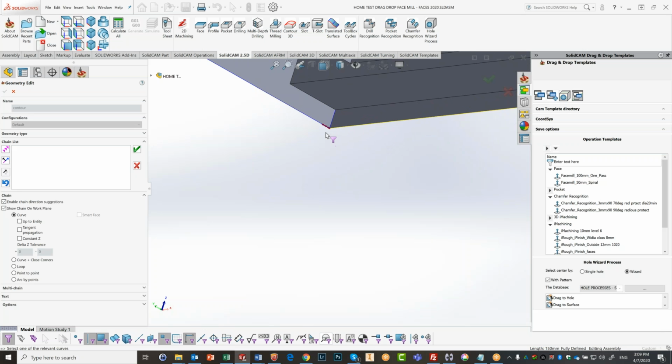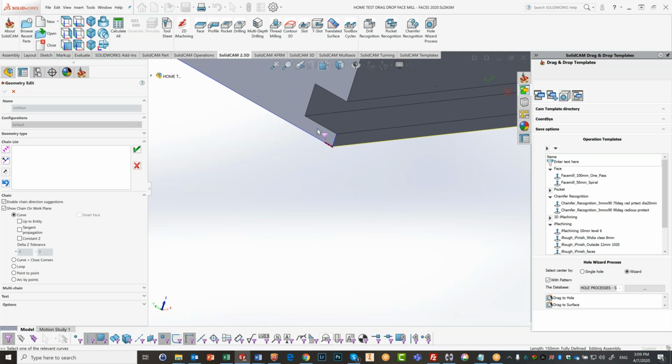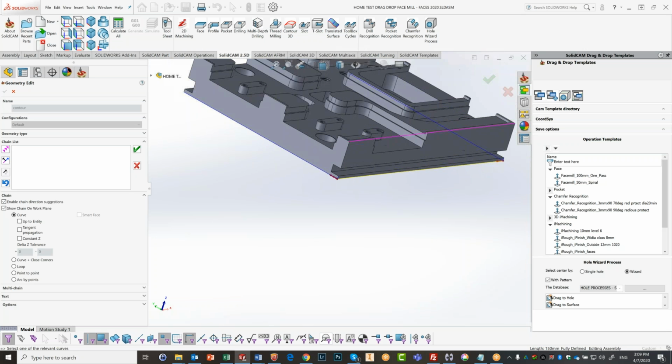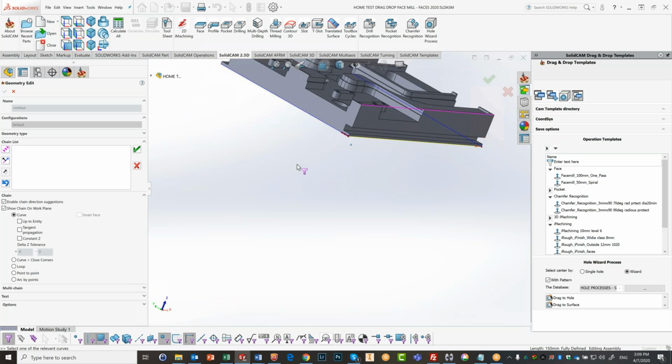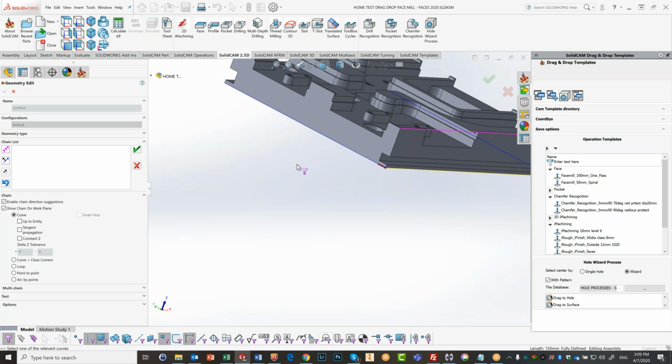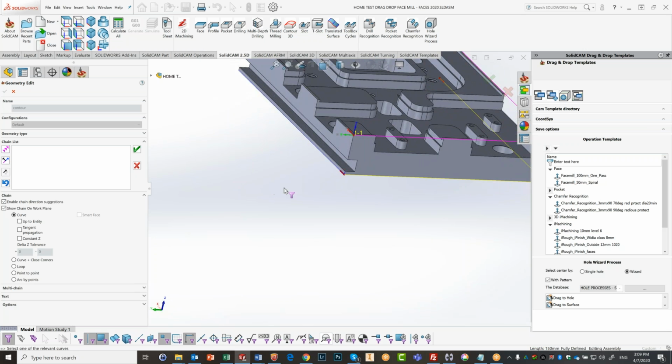Now, the suggested arrow gives me another option. Let me just zoom in a little over here. Let's go back to my left-hand side, and you'll note this over here, add selected element. So instead of me clicking on the lines, I can if I want to, click on add selected element. You'll note if I click on it, it'll choose and then go to the next element.